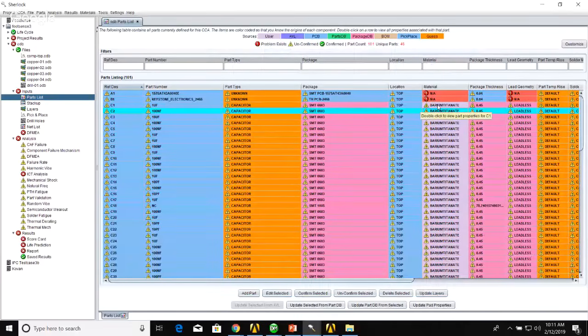In order to calculate the reliability of small components, we typically don't model it in full detail. We don't model the solder ball, we don't model the leads explicitly. Instead, we take the size of the package and using various reliability criteria, we typically look at things like strain and deformation to characterize it.